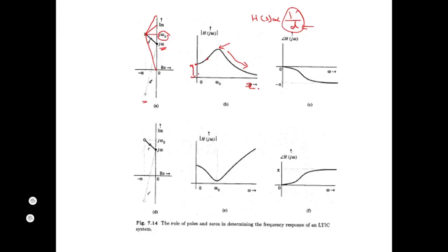It is allowing the low frequency components to pass through, and at high frequencies, it is coming down to zero. So it is a low pass filter. Okay. Similarly, if you measure the angle, you will find the angle varies between 0 and -π. Okay. So in this reverse sigmoidal curve phase, you will be getting this point.